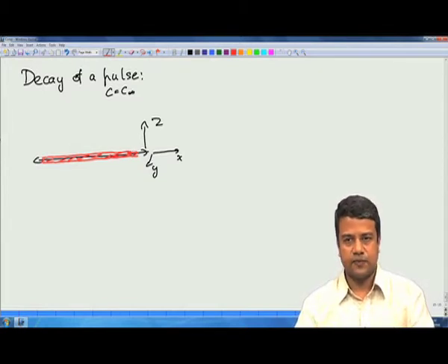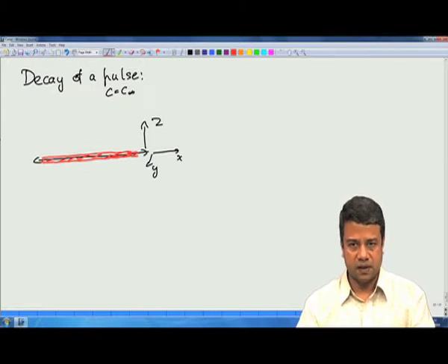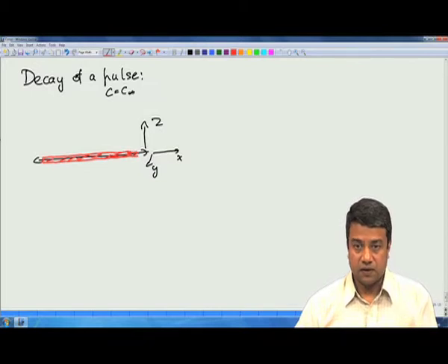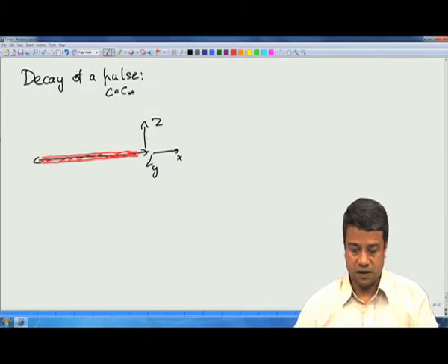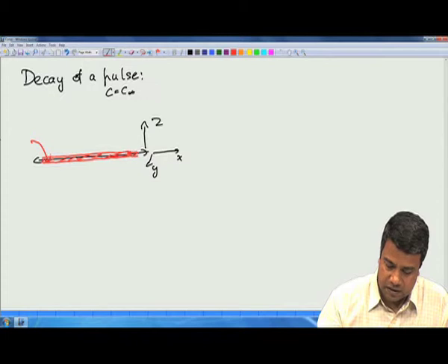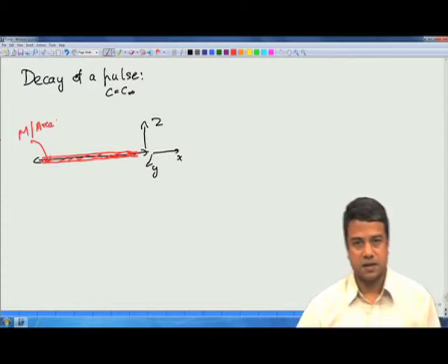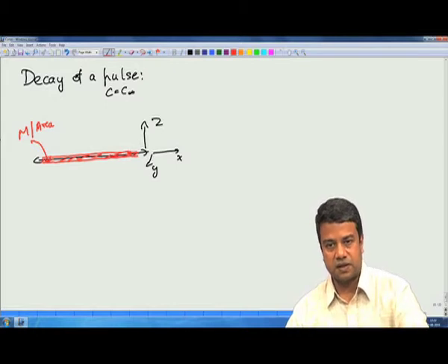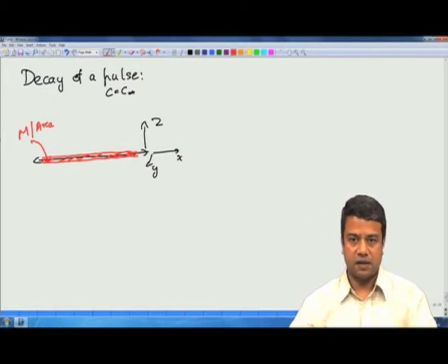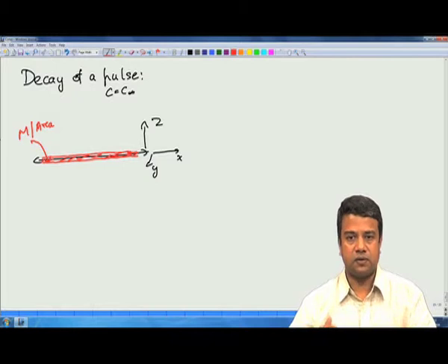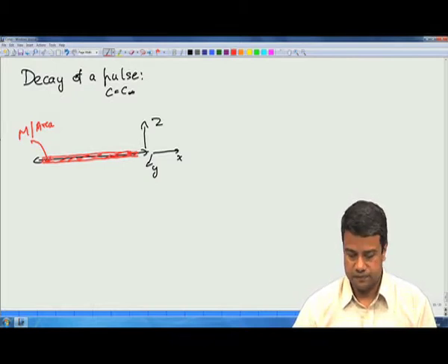In this case, the mass is per unit surface area in the xy plane. So, I do not define the concentration here, but rather the total amount of mass that is input is m per unit area, instantaneously inserted at this location. It is like generating a certain amount of mass instantaneously due to a reaction at this surface.